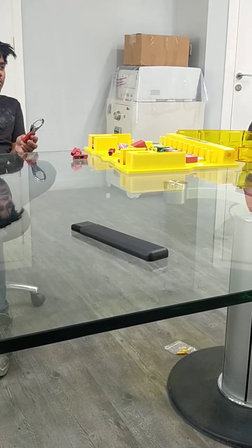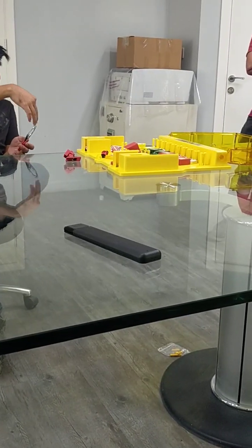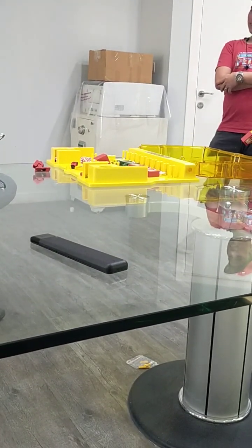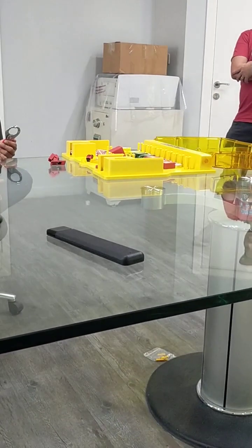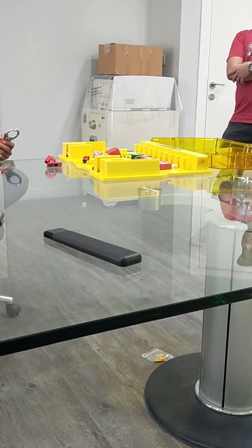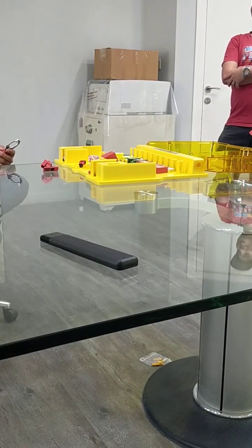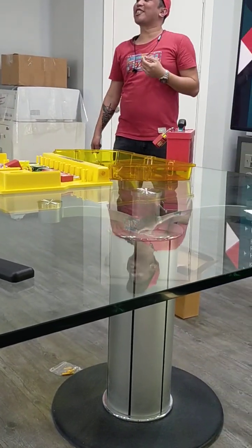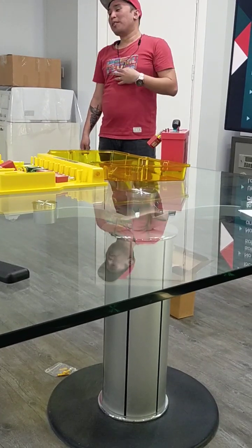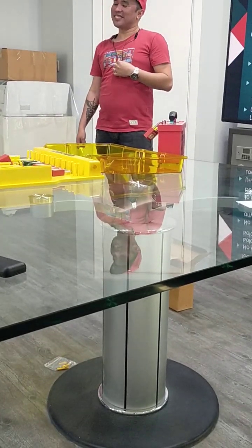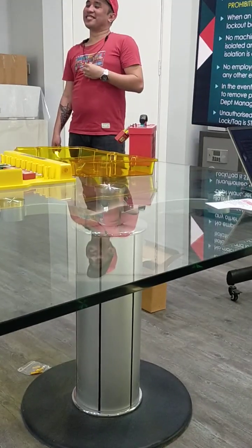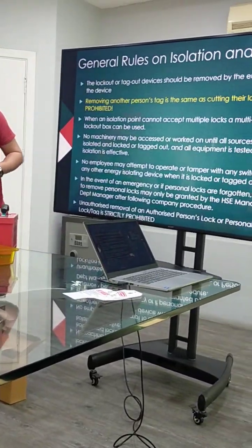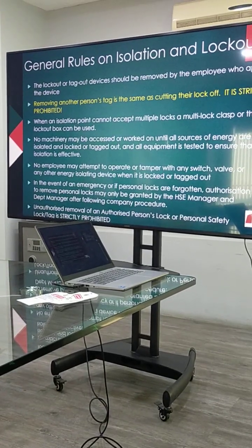Then, for example, he's doing work somewhere else. Then I go around. I saw his padlock. We need to start the machine. Rajesh, where are you? Sir, I'm in BU5. Is your job finished? Yes, sir. Then I have all the keys of my electricians. I will remove his padlock. Because I'm authorized, because I'm an engineer. I'm one step ahead of my electrician, so I have the authority to remove his padlock. Before, in our project. So if I open this padlock, I'm one step ahead of him, I'm responsible.